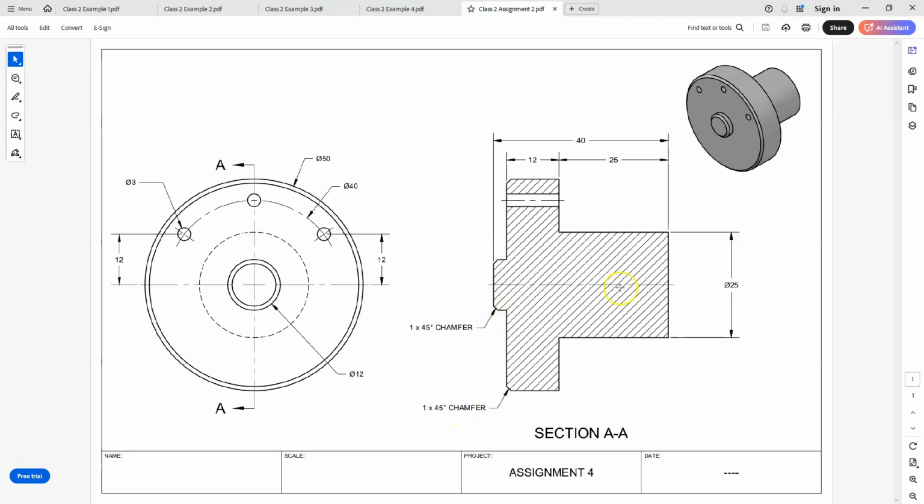And then finally, this other stuff that is going on, we'll take a look at the chamfer command, and we're doing a revolve command. There is no hole in the middle, so we can go ahead and use one of the lines that are on the actual sketch as the axis of revolution. But I'm going to go ahead and put an axis of revolution there anyway. Okay, so let's go ahead and jump over to SolidWorks and get started.